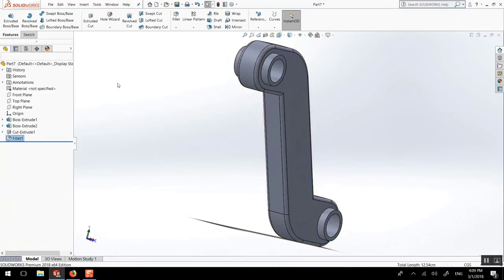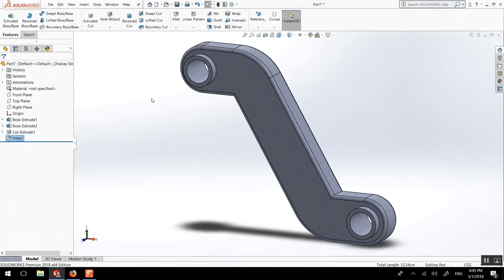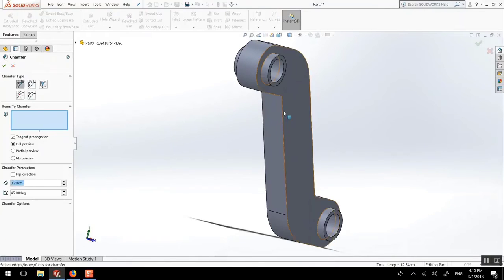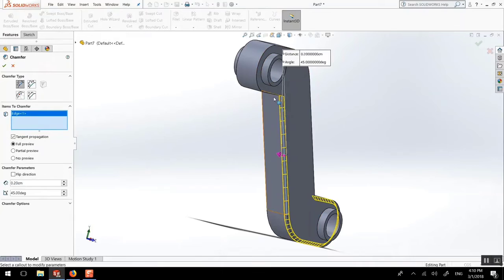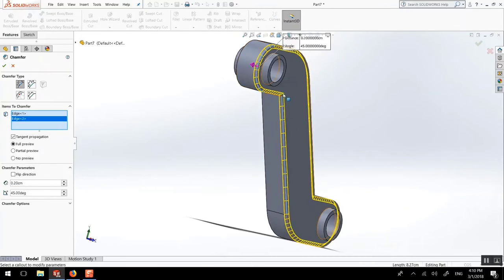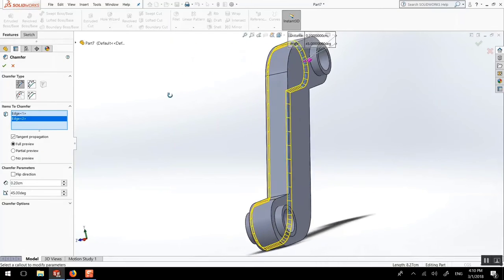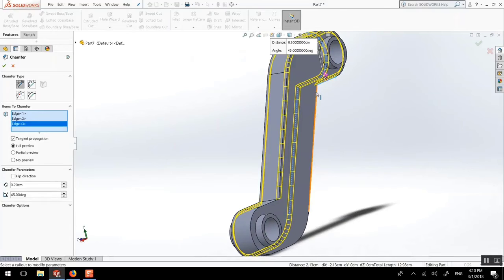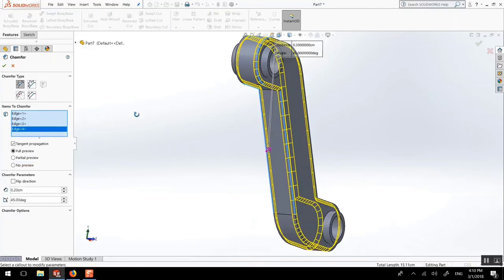And then you can add another set of fillet. Here, what can look very nice actually could be also chamfer with underneath. So we could try that. And then chamfer on the back.